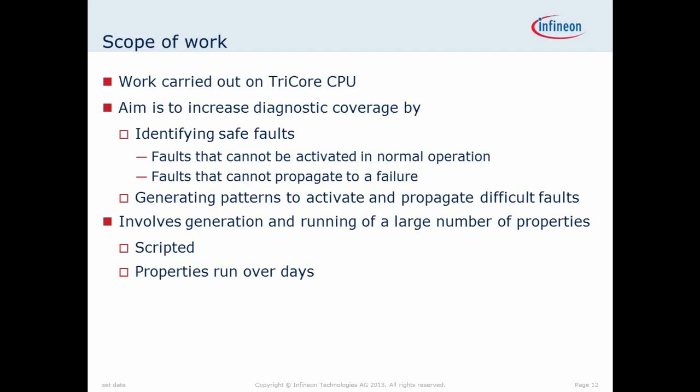So the aim of the work is to increase the diagnostic coverage, to give an accurate measure of diagnostic coverage, let's say, by identifying safe faults, formal identification of safe faults, and also by formal generation of patterns to activate and propagate some difficult faults. So these safe faults embedded down in some safety critical logic.